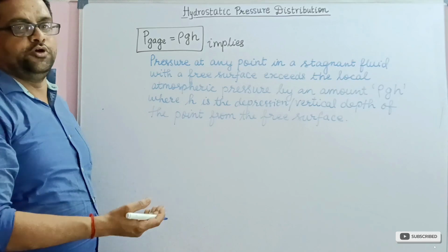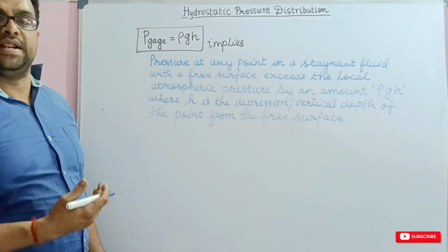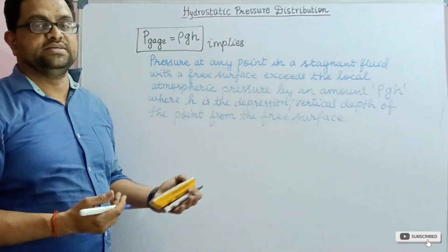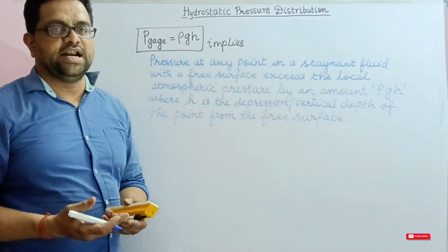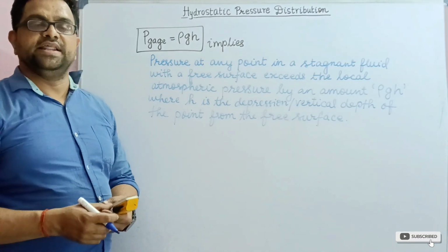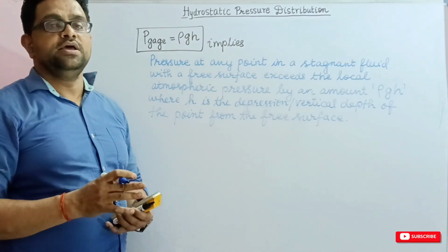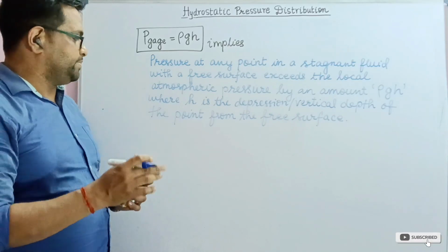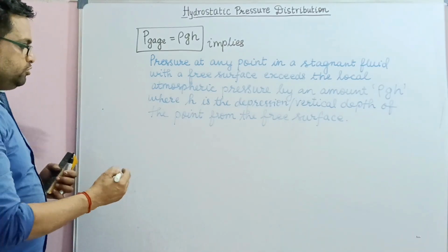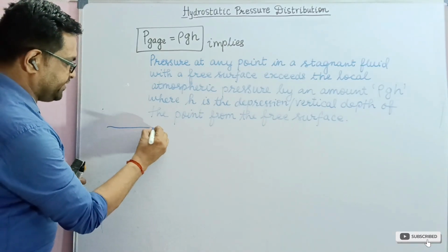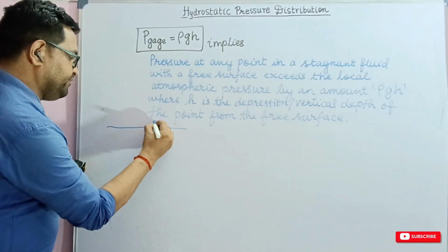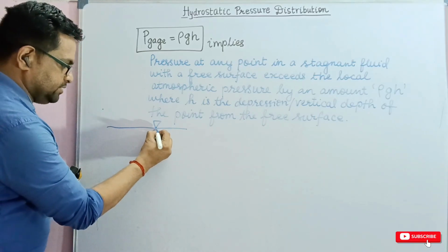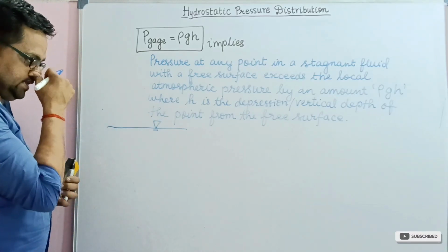in the vertical depth of a fluid. Now, the linear variation of pressure with depth below the free surface is what is known as the hydrostatic pressure distribution. Now, the variation of the gauge pressure in a liquid below the free surface can be illustrated as, suppose this is the free surface and we take various points. The free surface is indicated by using this.